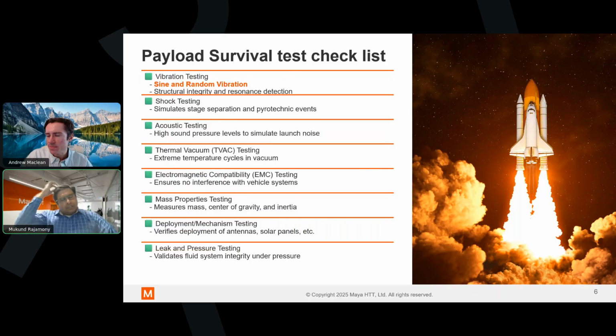The most pertinent certification standards for random vibration are primarily from NASA, the standards 7001 and 7002, the GSFC, the ESA for structures and shock, and the Department of Defense. They're widely used in aerospace and space qualification for components, and they might have dual applications as well for electronics and avionics. And then the SAE, they provide vibration testing methods and reliability practices, sometimes referenced in aerospace and hardware contexts. Next slide, please.